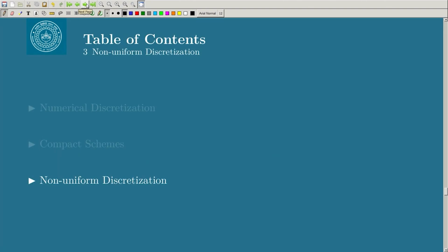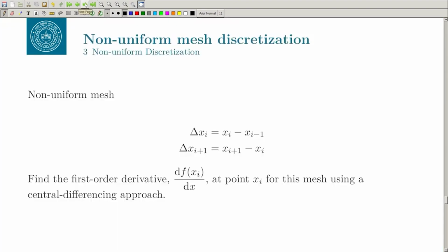One last thing I want to touch upon in terms of discretization is non-uniform discretization. Very often your grid will not be uniform. For example, let us say you want to calculate something on a flat plate. You will have the boundary layer developing like this, and you want to capture the events very close to the wall in the boundary layer very well. Outside, you know the flow is not that vertical; you might use the Euler equation, even the Bernoulli equation will be fine. But here there are a lot of things happening. Your velocity is changing very quickly.